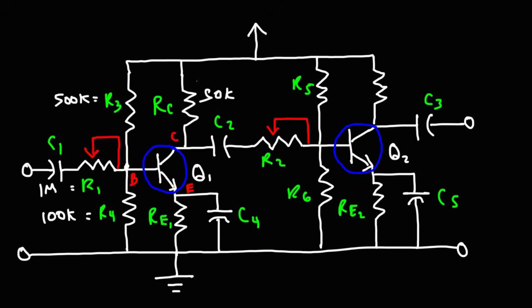Now let's adjust our RC and RE values. Since R3 is set to 500 kilo ohms, I want RC and RE to be less than 100 times smaller than this value. So if you divide that by 100, you get 5 kilo ohms. If I were to use a value of 1K for RC and 1K for RE, then beta could be at most 250.